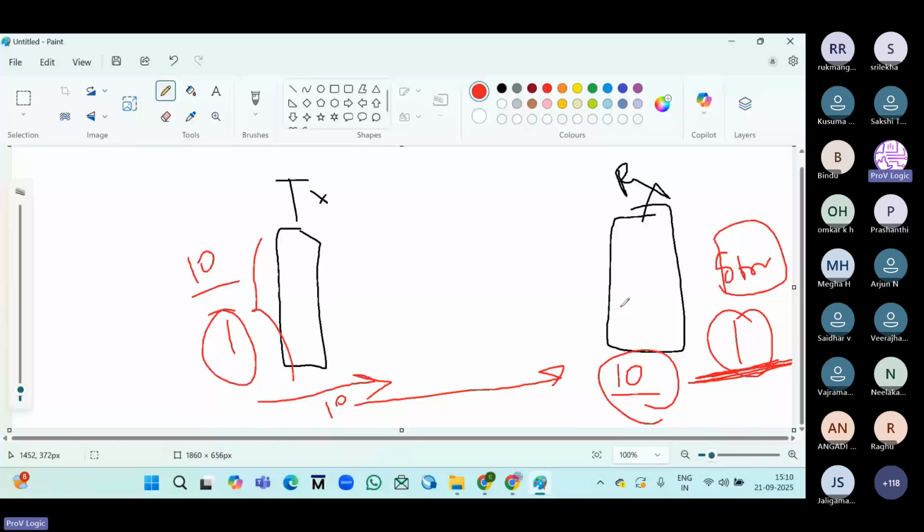Okay. A latch is also storing single bit data, right? Which one is mostly preferred in real time, a latch or a flip-flop? Flip-flop. Because a latch is level triggered, if there is any change between that level, there will be loss of data. Therefore, flip-flops are used because the changes can be noticed as it is edge triggered.